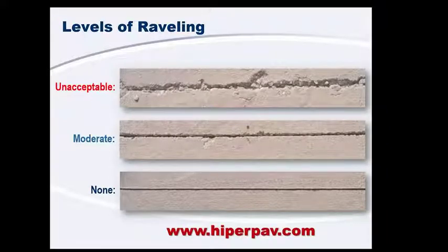So one tool that's actually very useful in helping define when to get on the pavement and start sawing our joints is HIPERPAV. Now this was a program developed by the Federal Highway Administration. It's a free tool. You can download it at hyperpave.com. I believe we also link to it in our app library. But it's a really useful tool. It predicts that early stress development and the strength gain based on the actual environmental factors as well as the material factors, basically what our mix constituents are that are going to drive that hydration reaction and that strength development.